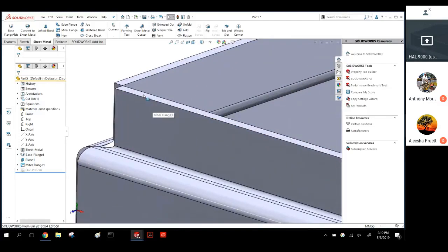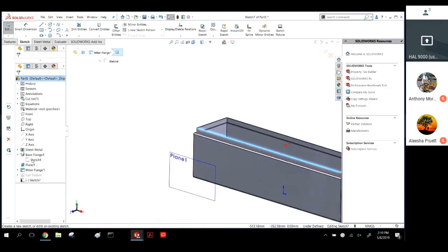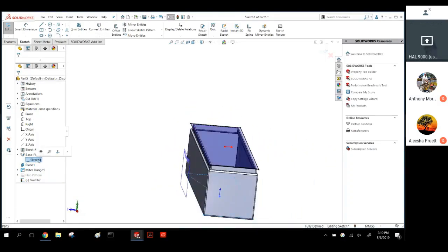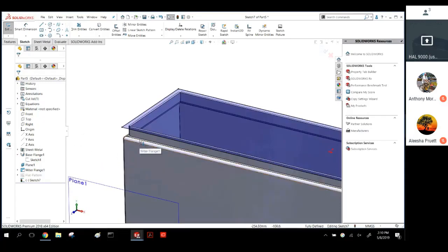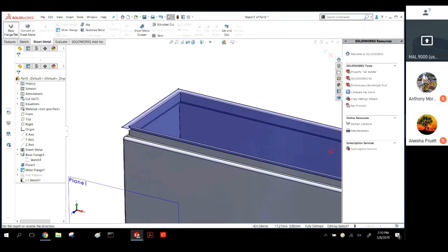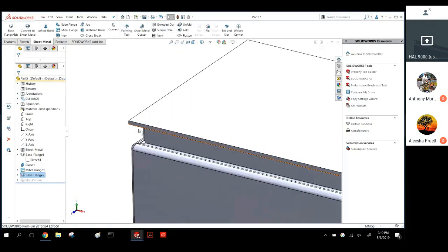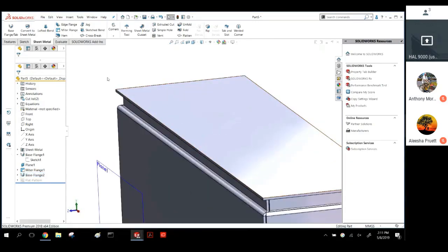All right, with that said, where I'm going to put this lid is I'm just going to start a sketch on the top of the box. And I'm going to convert the bottom of the box, that same sketch that I used to create the box, I'll use to create the lid, and turn it into a piece of sheet metal. By default, SolidWorks has the merge results turned off when you're doing multi-bodies because you don't want to have your sheet metal just one of them working like that. You want to be able to see both of them.